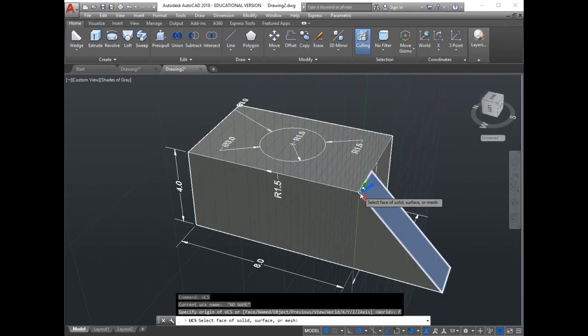Anyway, what if I decide to locate it somewhere here? Be sure before you pick up your point that this surface is the active one. So you can simply pick up this one, but I was not picking up that vertex, guys. This is the reason that I was not able to locate that one. Here you go, I can pick up this one as my vertex. See guys, I'm not caring about the first choice because the first choice is not for everything. It's only for the origin.